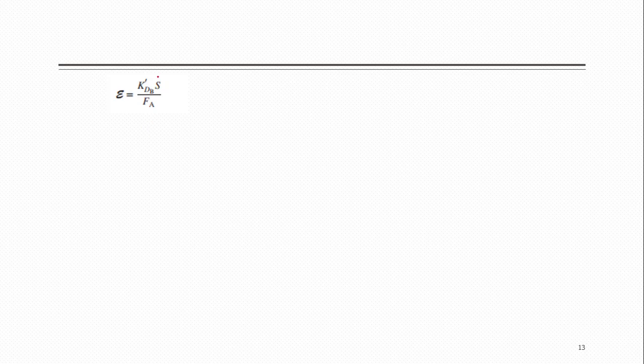What we are looking for? We are looking for S, solvent flow rate, and this epsilon maybe we can calculate, we will just look at that. Then this K is given in the system as well. Fa, you know, it is given in the system. How it is given? You know that there is total flow rate 13,500 kg per hour, and out of that flow only 8% is acetic acid, so 92% will be your water.